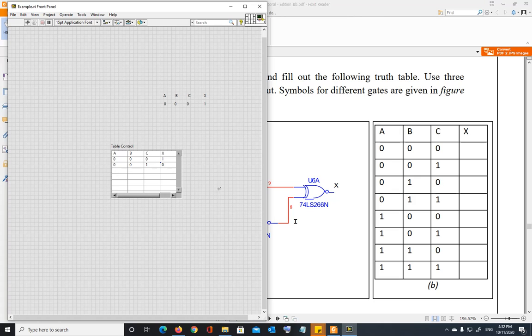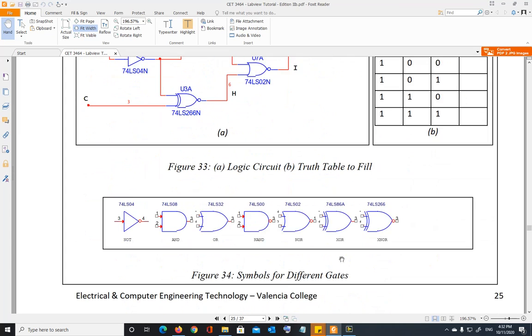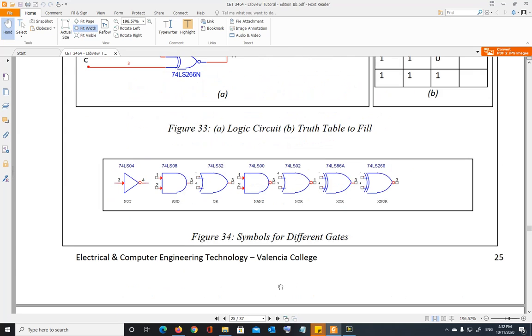Now, if you don't do the current values initialize, if you just leave it at the default, which basically erases all the values once you restart the program, then even if you put any value here, it is not going to show any value. So make sure if you're using this table, always right-click, go to data operations, and make the current data default. Or you can just type the table. When you're doing this exercise, please keep that in mind. And in the next video, we're going to discuss matrices and arrays.